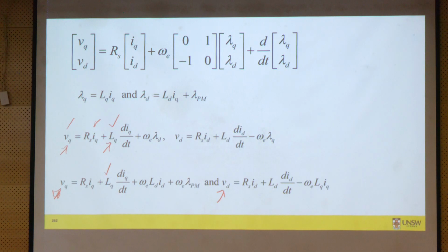Okay, and using these two equations, we can also use even Laplace transformation if we wish to analyze its responses, just like DC motor, okay? Or we can use these two equations to develop models. Like in Simulink, some of you may have got exposure to the Simulink PMSM model, right? So if you open that model and go under it, in fact, they have these equations only. So they only do calculation using these equations, the torque calculation or the response calculations, okay?